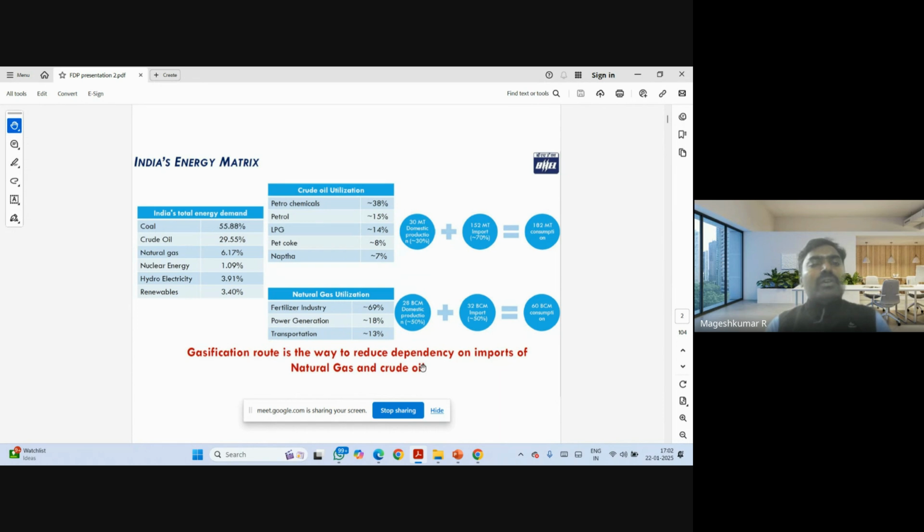And again, with respect to the quality of coal, if you recollect from our engineering, we would have studied bituminous coal, which, based on calorific value, is numbered as G series grades: G11, G12, G13, like that. Our grade of coal has a slightly lower calorific value when compared with the imported coals. It is a bituminous coal, and Indian coal is mostly, around 75%, high ash coal.